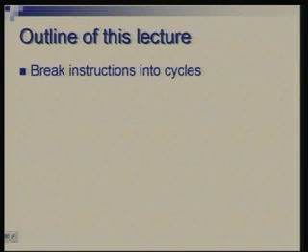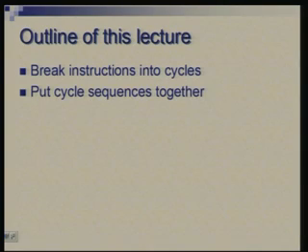So, we will look at what are the actions which are done in different clock cycles for various instructions, and then by putting these sequences of actions together, we will try to build the flow of control for carrying out these instructions.